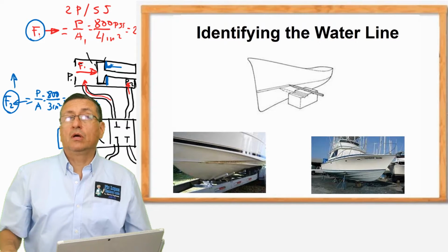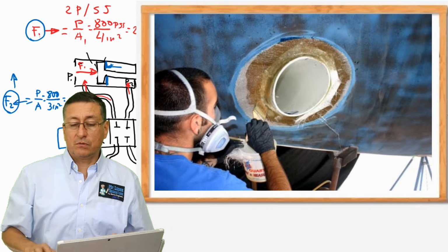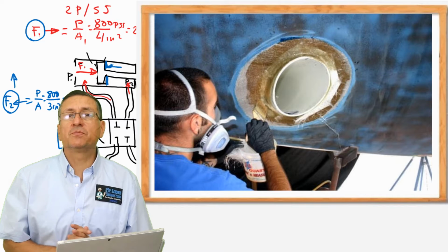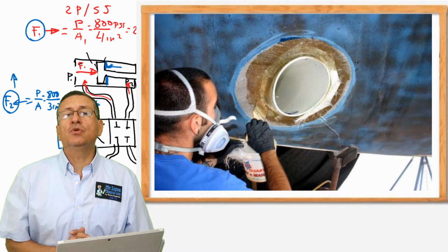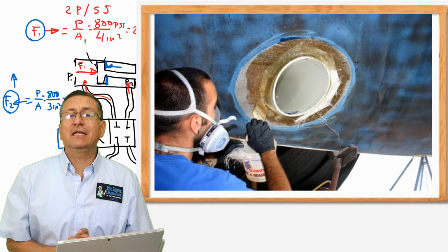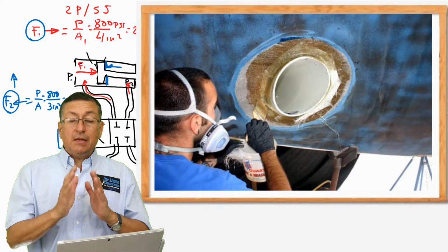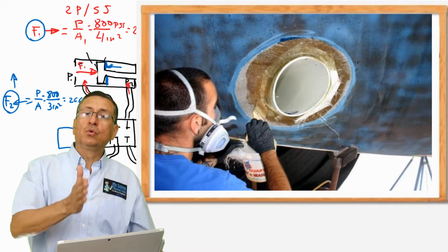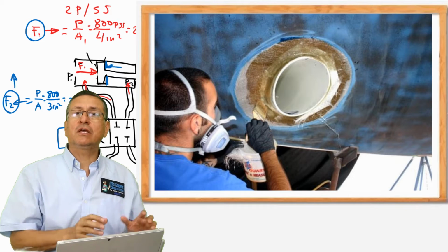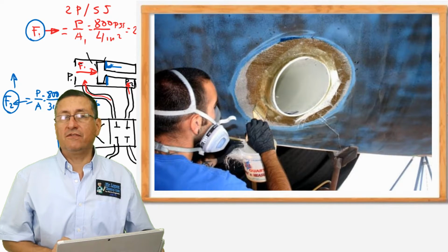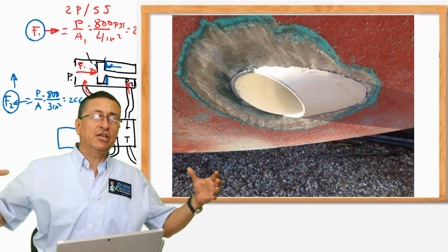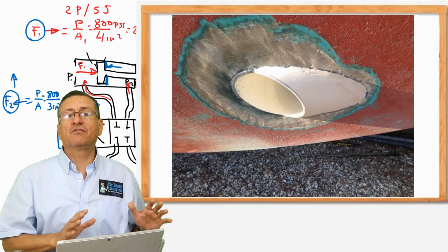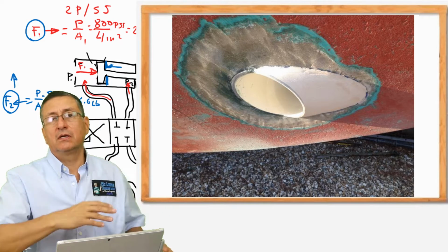In order to do the hole, install the tunnel and laminate the tunnel, I recommend, if you don't have enough experience with fiberglass, try to use a contractor specialized in the installation of the tunnel. Let me explain something. The installation of a bow thruster has two different sections. One section is the fiberglass. The fiberglass is the hole, the installation of the tunnel, the lamination, all the process of fiberglass, and after that painting the bottom.